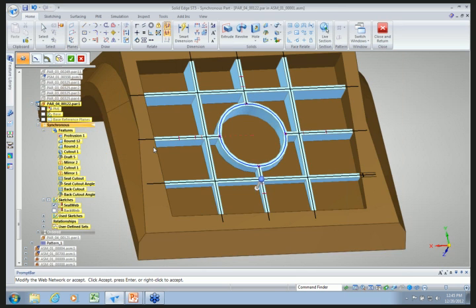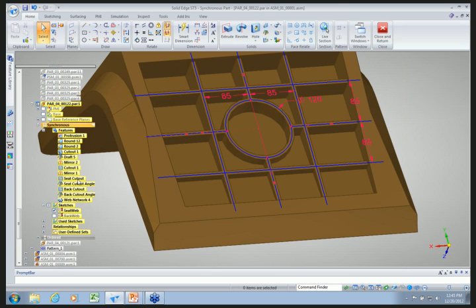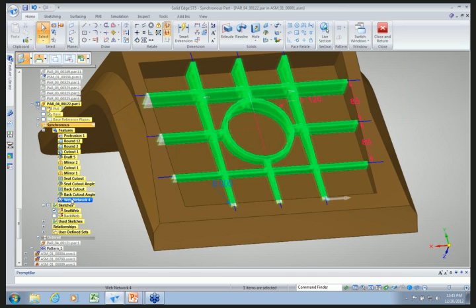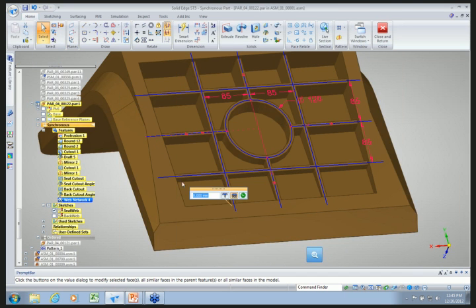And instead of entering the thickness up in the bar, we enter it in the box that shows up here. So for this, we want to go ahead and make it 8, and we want to go ahead and add, sorry, I needed to add draft to it. So we'll just go back in to edit it.